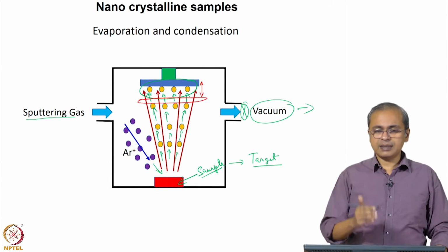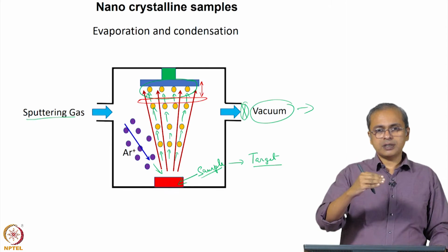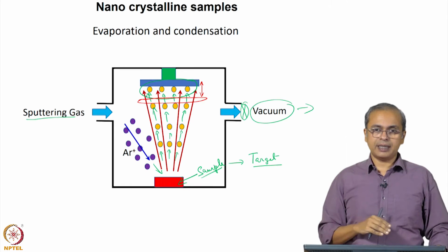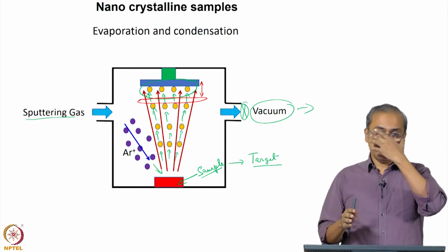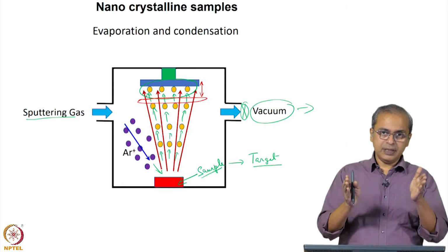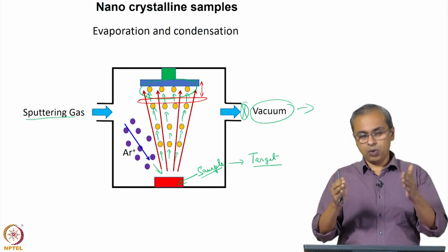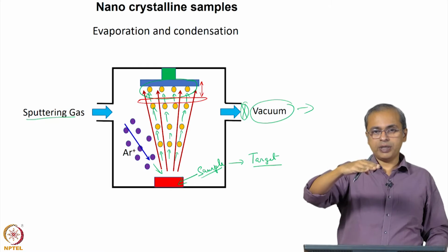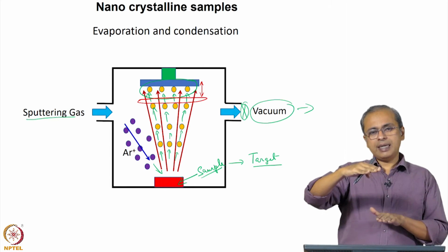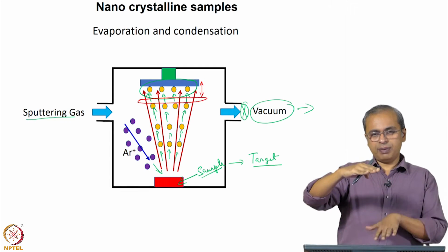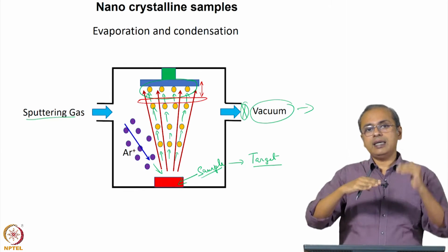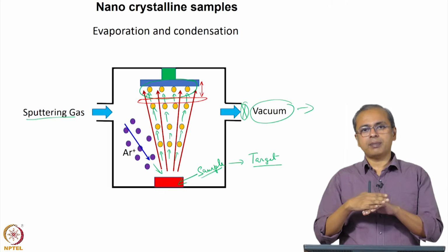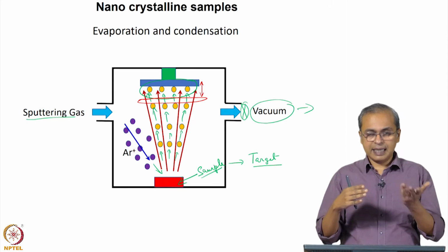So it is between the substrate and the target, and it blocks whatever is coming from the target from reaching the substrate. So usually what will happen is, in these experiments we start the process, we allow some amount of sputtering to go on with this mask blocking the path, and so at that point any impurity that is getting released from that sample will not reach the substrate. It will get blocked by this mask, it will maybe form a layer on the mask, and that is useless for us.